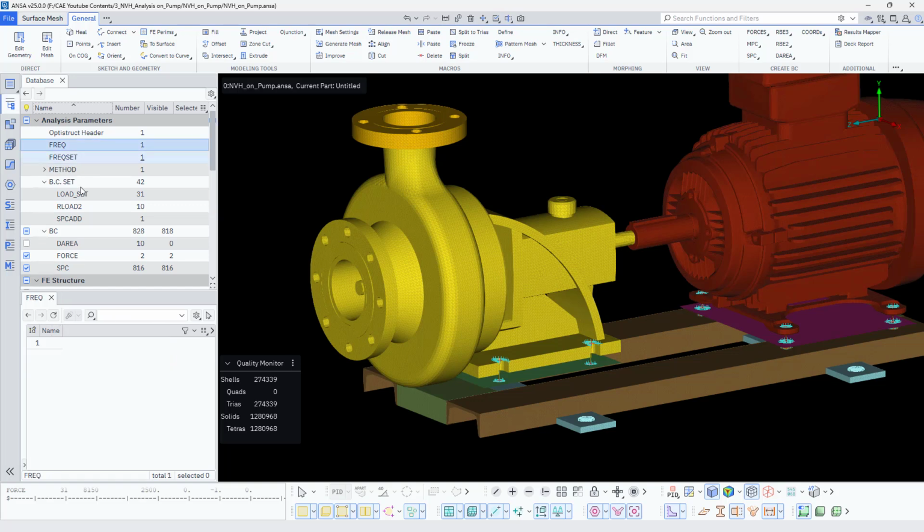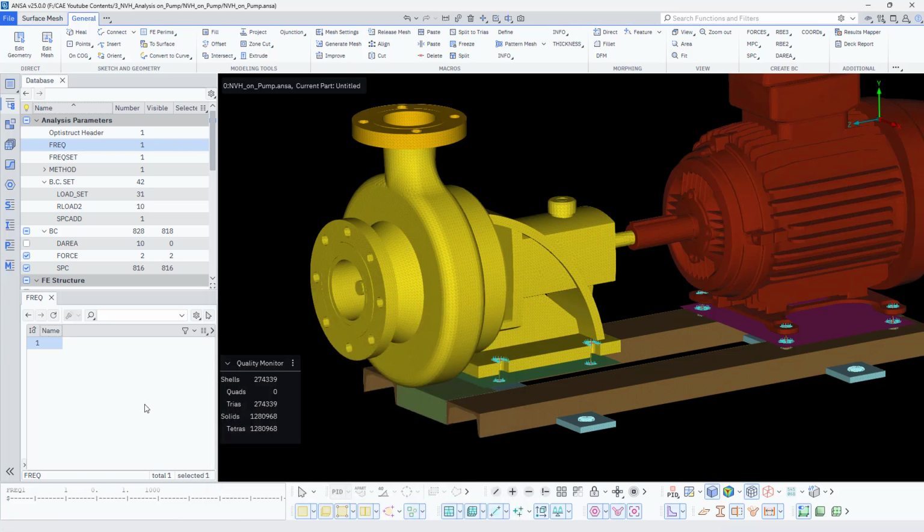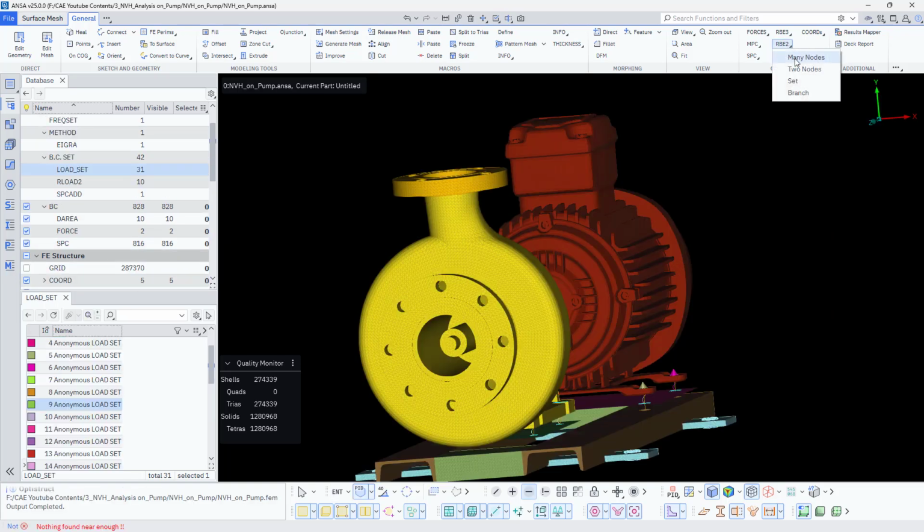Yep. So I think most of the things are done. Now here I would like to change it, because if I take each and every increment, it will take a lot of time. So what I'll do is 5 increments. I'll take 0, 5, 10, 15, 20 like that. Here multiplication of 200, if I do it up to 1200, like 1000 hertz will be there, right? So I can just define it as 100 here. Sorry, 200, 5 into 10, yeah, 1000 hertz. Just to save the runtime. So I just did this particular change, guys. You can even run the same.